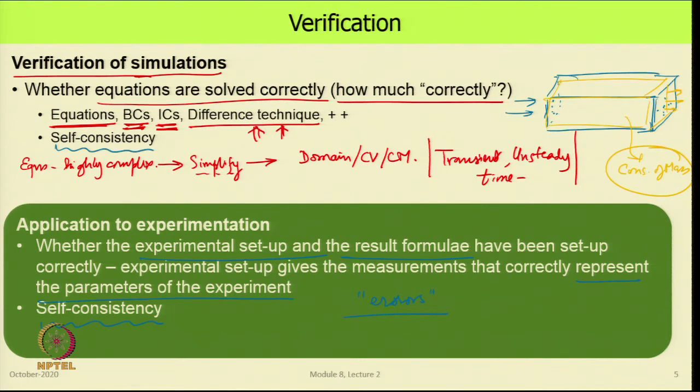And that is very simple, that if there is steady state operation, then the mass flow rate going into this face, m dot in, has to equal m dot out. And while we will say that theoretically this is always going to be true, in practice either method will tell you that my inflow rate was this much, outflow rate is this much, and there will always be a difference between them, whether it is the numerical simulation or the experimental work.